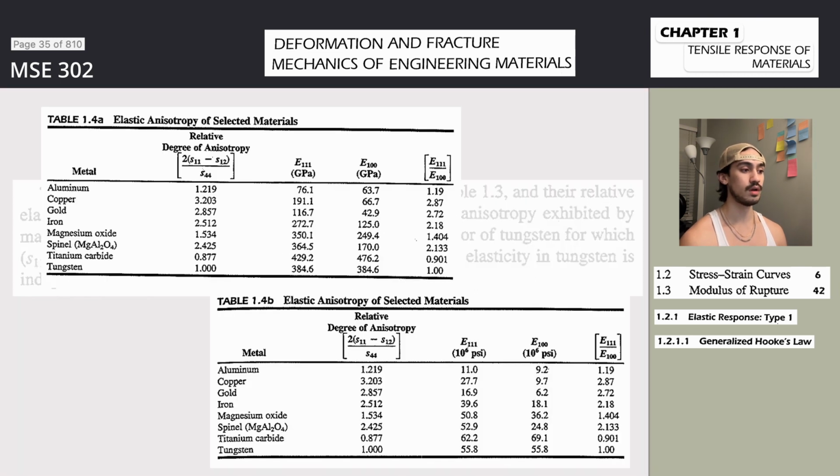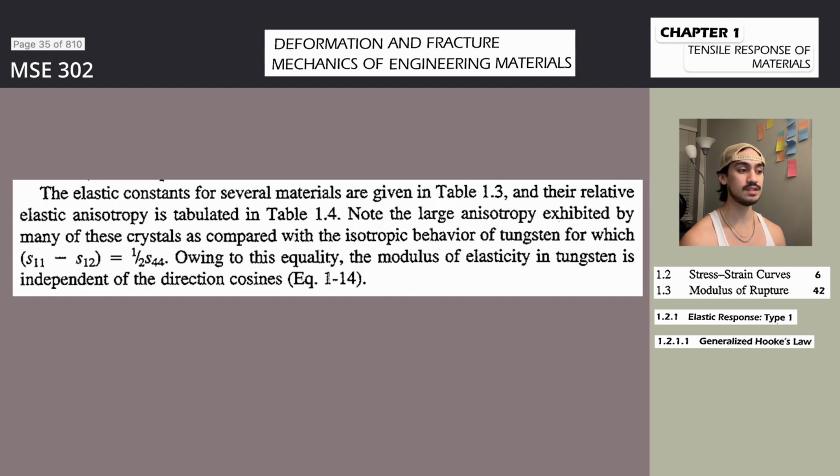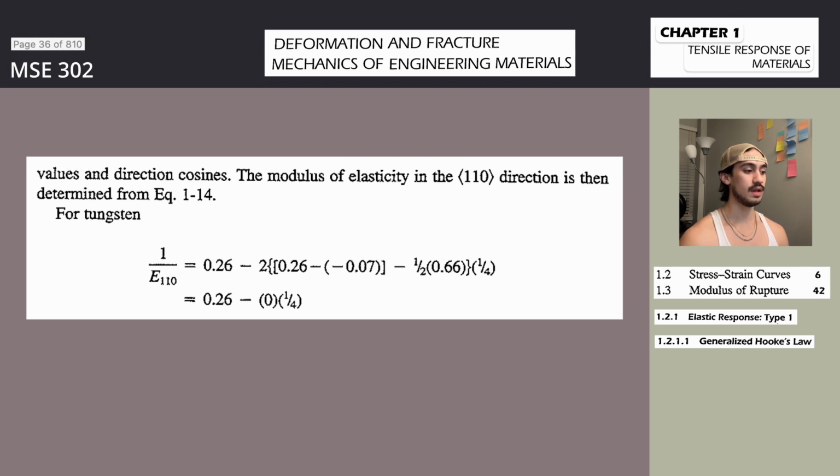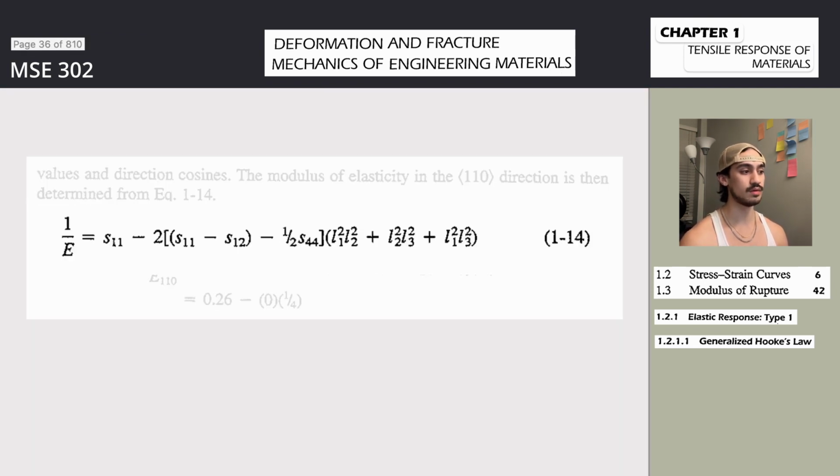1. Determine the engineering stress-strain curve, such as the one in Figure 1.6. 2. Construct a line parallel to the elastic portion of the stress-strain curve, the sigma-epsilon curve, but offset from the origin by a certain amount. The generally accepted offset is 0.002, or 0.2% strain. And 3. Define the yield strength at the intersection of the stress-strain curve and the offset line. As cited above, this value is usually defined as the 0.2% offset yield strength.